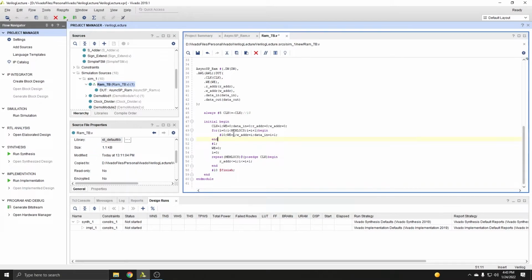So what I personally do to handle this is I just usually drop a simple #1 delay, just to make sure that it doesn't happen at the same time. You don't have to worry about that too much. Just remind yourself, though, that if you wanted to continue using this delay method, then what I would recommend to get to the next clock cycle is to delay 9 rather than delay 10, because of course if you delayed 10, it'd be after the clock edge. But since I'm using the next technique that I'm going to show you, that's not required in that case.